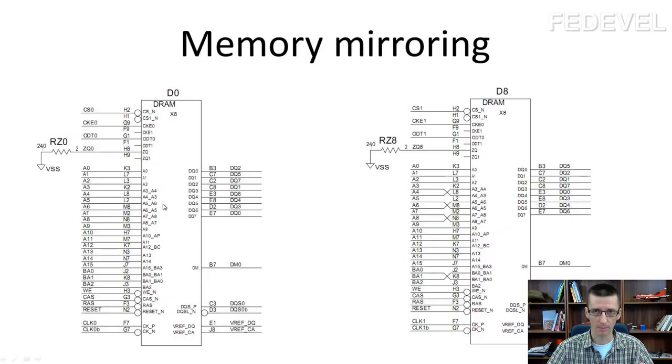They connect the top memory chip exactly the standard way as we also do it. So the A3 signal is connected to the A3 pin of the memory chip, A4 is connected to A4, A5 to A5, A6 to A6. If you have a look at how the bottom memory chip is connected, you will see something different. The A3 signal is connected to the A4 pin. The A4 signal is connected to the A3 pin. Okay, and here are some other signals.